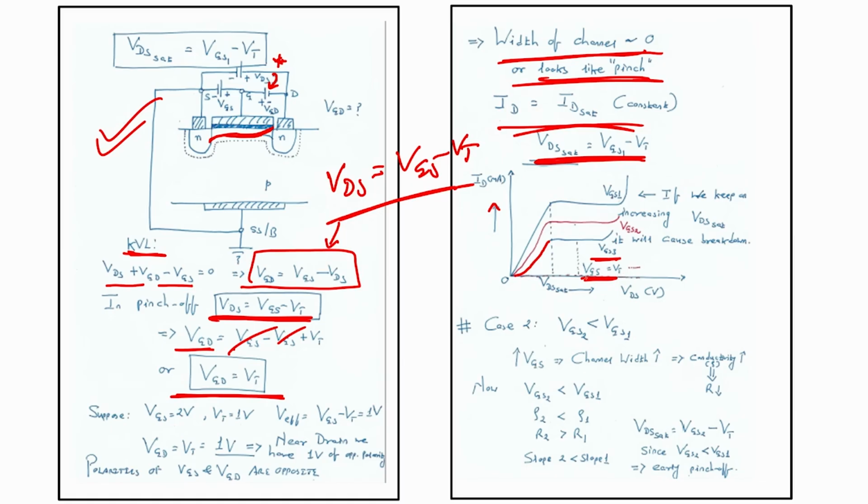Above the value at the bottom where VGS equals VT, as soon as VGS is greater than VT, my current can start flowing. We have seen this in the first slide, right. That means on increasing voltage I can see an increase in current, depending on how much VGS we are applying. So, if I keep on increasing my VGS, I can obtain higher current, and this particular region is the saturation or pinch off region.